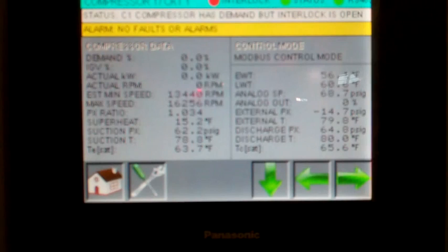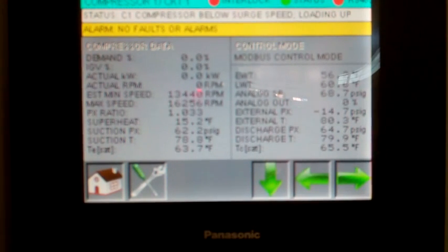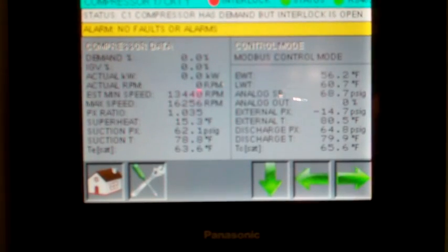Starting from the top, you'll notice that you have a date and time stamp. Friday, April 29th, it's 2:22 in the afternoon. Next thing you'll notice, you have your interlock, your status, and your RS-485. Right now we're showing a red interlock. That red interlock is there because circuit 1 is not running. The flow has been shut off to circuit 1. Okay? In fact, you're looking at circuit 1, compressor 1 right there.